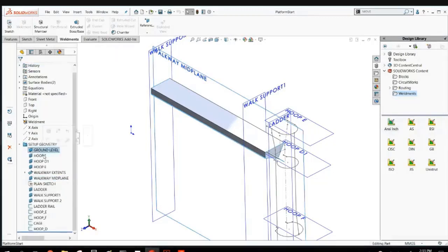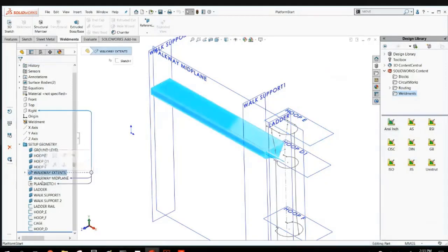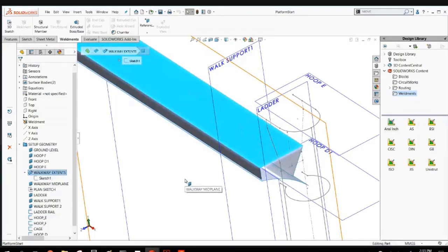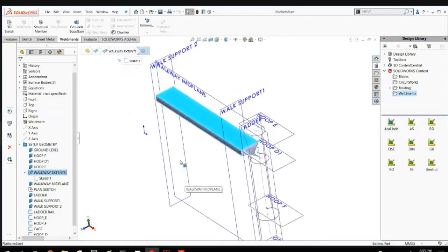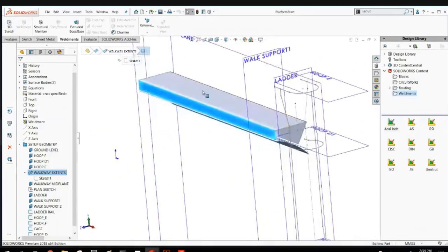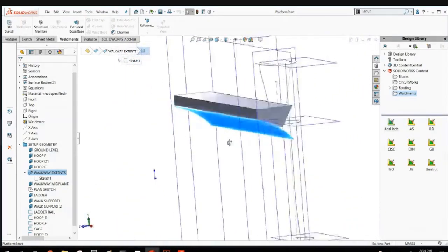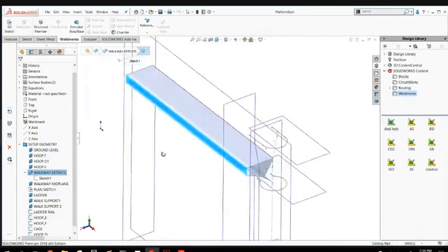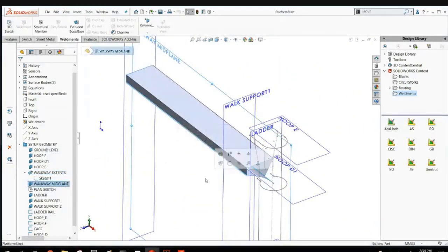So what I did was I created some reference planes for where things are. Then I also created a surface similar to the surface that was created for me automatically by that 3D grid system. Because this is nice, I can see, okay, this is where the top of it is. This is where the tank itself is. Here's where the legs come down. So I get an idea in 3D space where this thing's supposed to be.